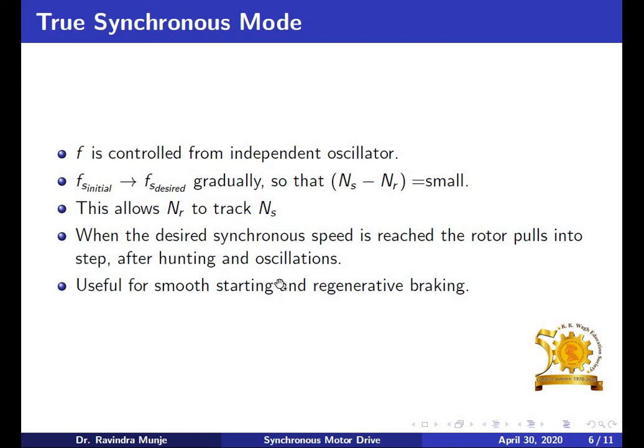When the desired synchronous speed is reached, the motor pulls into step, which means it goes into synchronism after hunting oscillations.